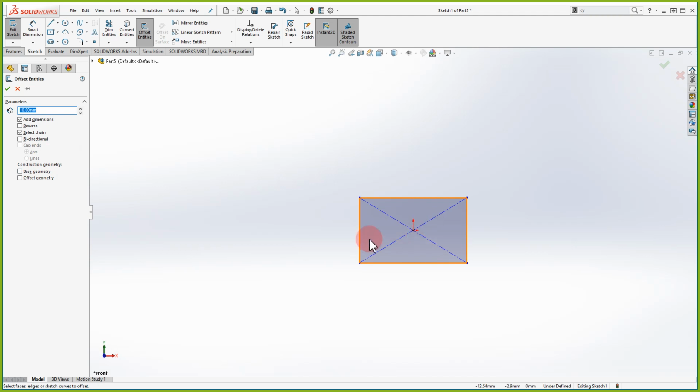Now watch. If I want to go 10 millimeters, I click on where I want to go on this object here. And right now it's going to keep a distance of 10 if I want to, right there. If I want to go inward, I go reverse, and now it's going 10 inside. If I want to go both directions 10, now I could go both directions, right? If, for example, I wanted to go smaller, let's put it to 5.